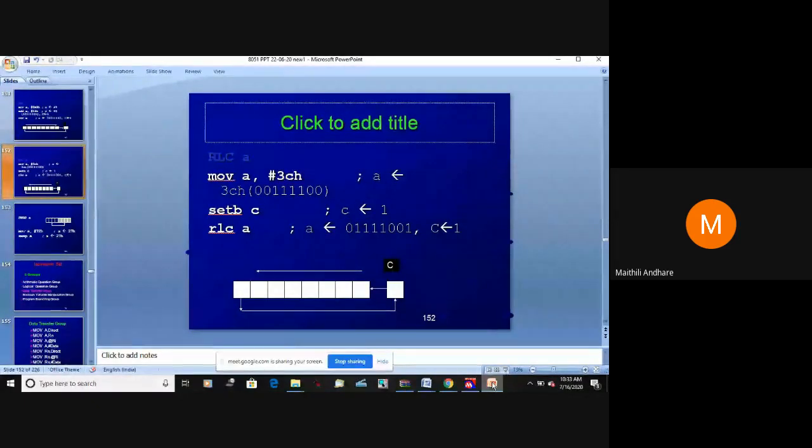Here I am setting the bit which is called the carry bit, and then I have used the instruction RLC. So you have to see the format of this instruction, from which bit comes in which position, and according to that you have to shift. These are very, very simple operators. For that purpose, 4 instructions are available in your 8051 microcontroller. You have to remember, for shift operators, how many instructions? The 4 instructions: RR, RL, RLC and RRC.